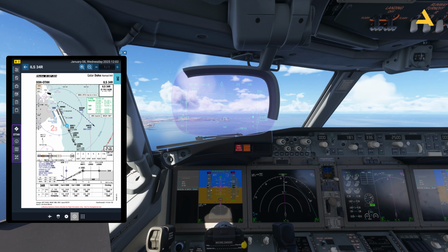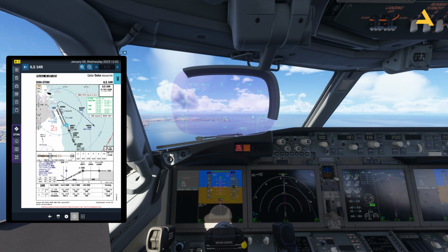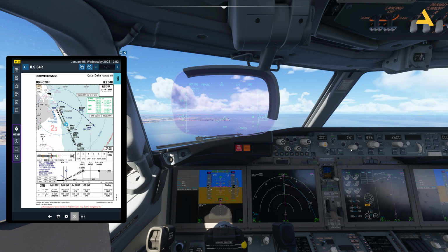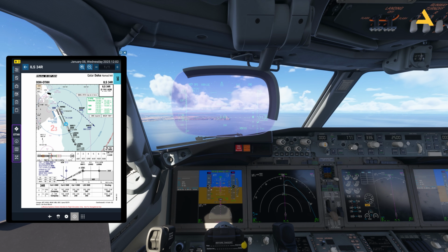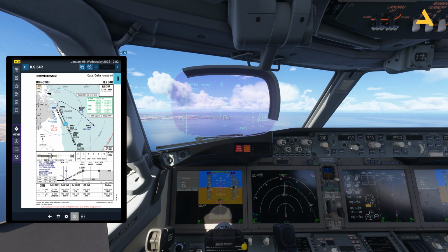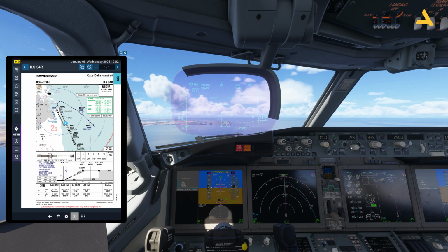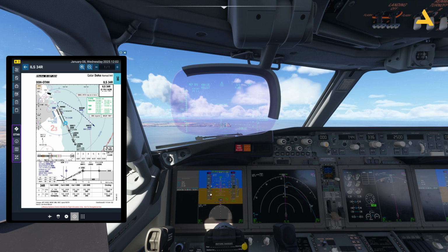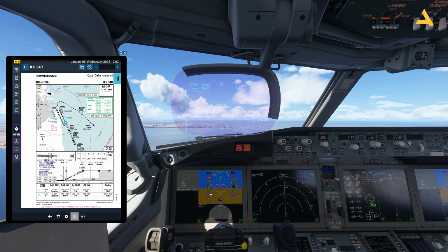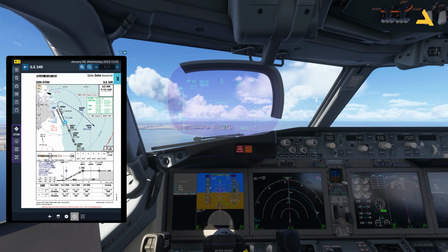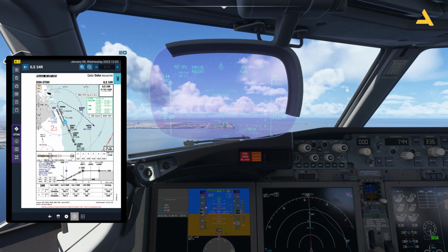And now I can lower the gears and extend the flaps. And now, as the speed is not controlled by the autopilot, I have to reduce it, 144 knots. This is the speed for the approach. Now you will see that the speed is also reducing. Now landing gears down, full flaps, and if you look at this small circle, it should be in the middle.